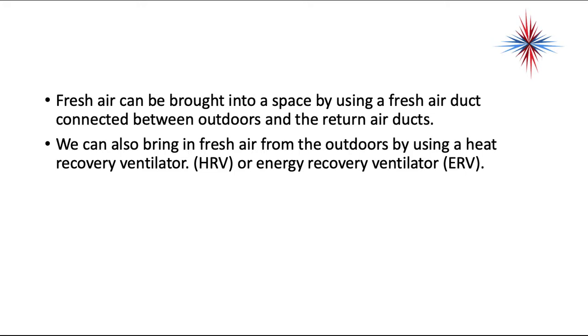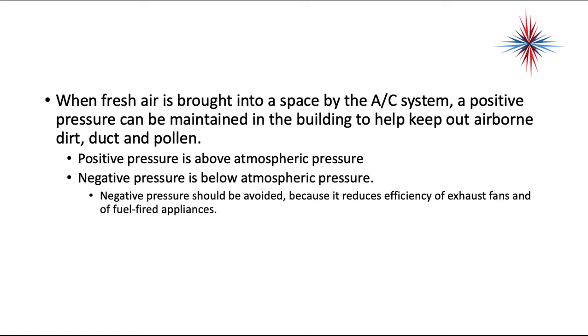We can also bring fresh air from the outside by using a heat recovery ventilator, HRV, or an energy recovery ventilator, ERV, depending on what part of the country you're in. When fresh air is brought into the space by the AC system, a positive pressure can be maintained in the building. This will help keep out airborne dirt, dust, and pollen. Positive pressure basically says the building has an air pressure above the atmospheric pressure found outside. Negative pressure is below the atmospheric pressure outside.